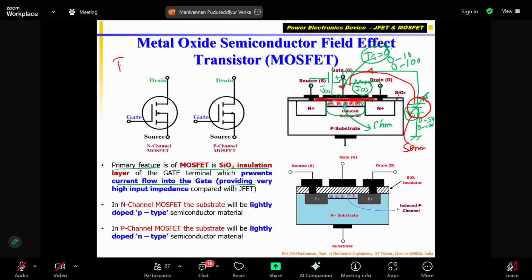Please note that transistor and JFET both will consume current when I give voltage. Transistor consumes more compared to JFET. Okay, so that means transistor has more loading effect. Please know that it cannot be avoided, but still we are using it. And JFET has higher input impedance at the gate, so it consumes less current.